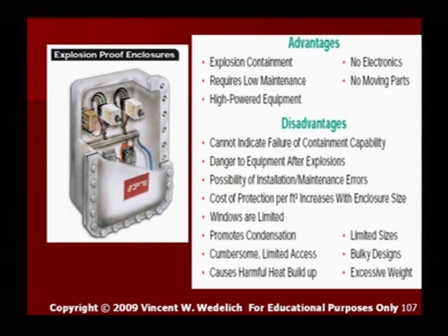Another disadvantage is danger to equipment after explosions. Obviously, the explosion occurs inside this box, and the internal equipment can be damaged from that explosion. Possibility of installation maintenance errors. Cost of protection per cubic foot increases with enclosure size. Well, that's true because these enclosures are limited in size. Usually they are about 3 foot tall, maybe 3 foot wide, and about 16 inches deep is about as maximum as you're going to get one of these.